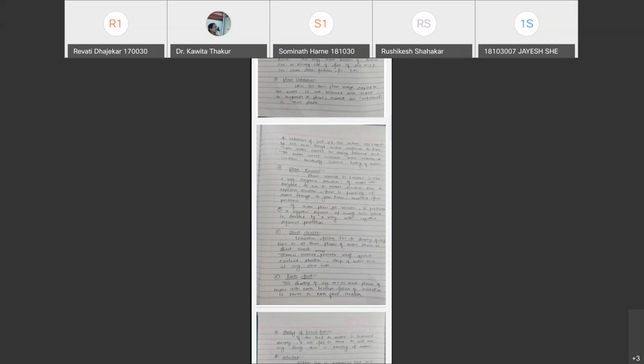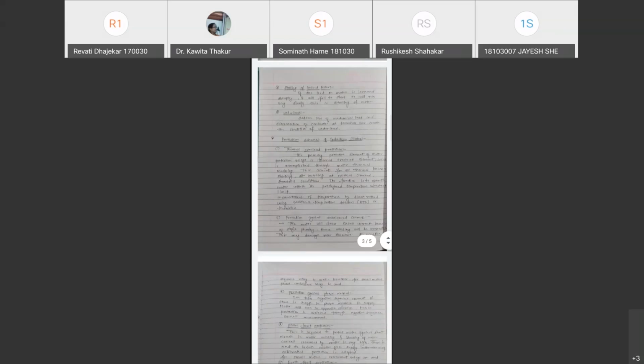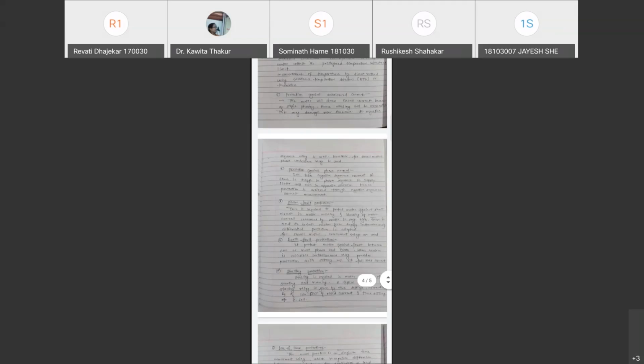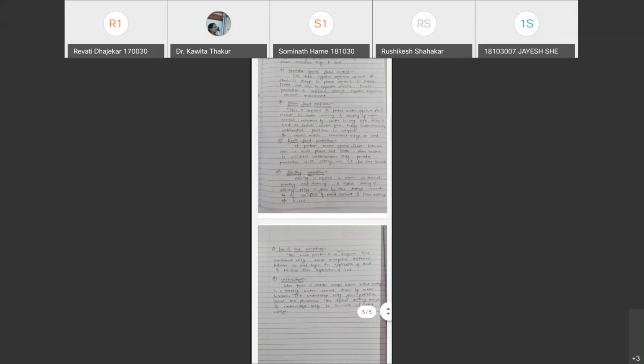The typical setting range of under voltage relay is 70 to 100% of rated voltage. And next is loss of load protection. The usual practice is to use the definite time overcurrent relay, which recognizes the difference between no load before the application of load and no load after the application of load. So in this way, induction motor is protected against faulty conditions.